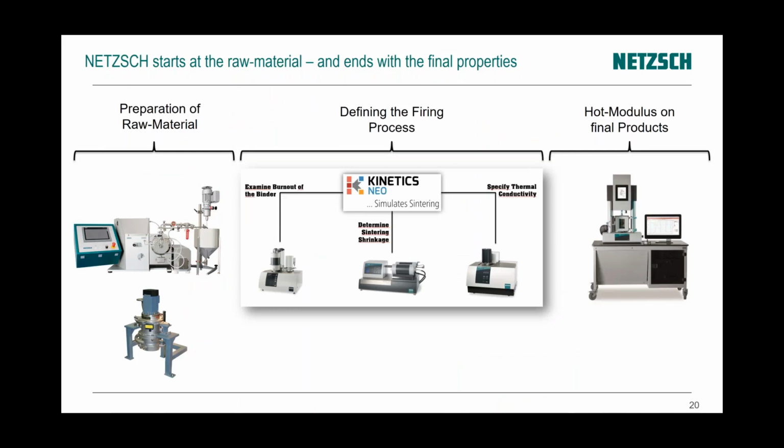So the thing that we discussed during the live presentation was in principle the middle of this process. Where we talk about defining the firing process, we have some helping instruments in our portfolio: the thermogravimetric analyzer, the dilatometer, and the LFA for thermal conductivity measurements. All those data can be used for optimizing your sintering process with Kinetics NEO, our simulation software.